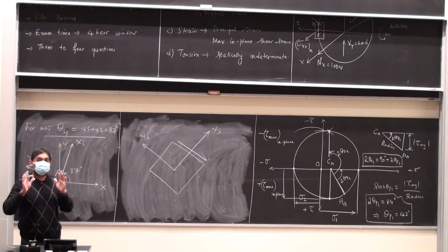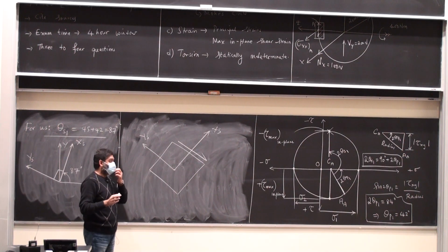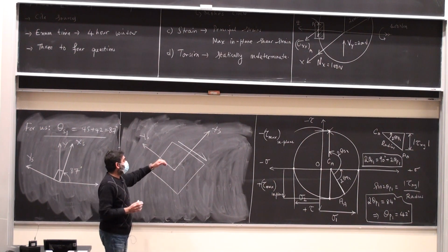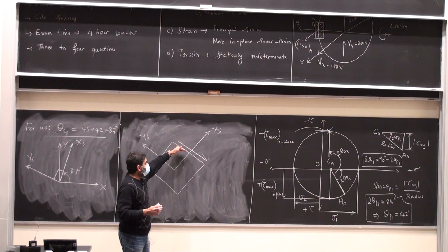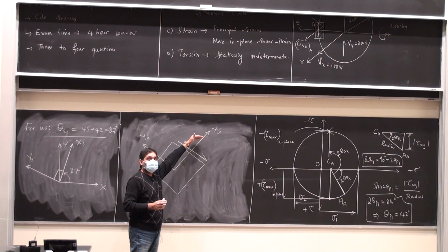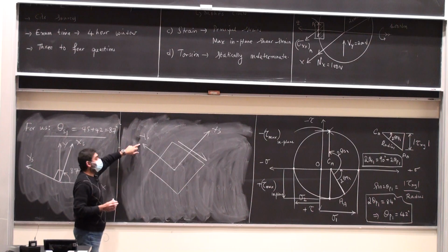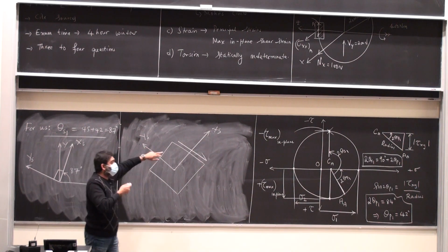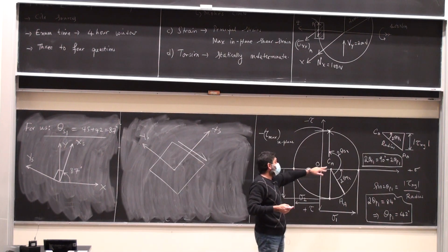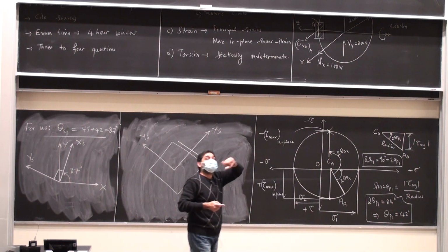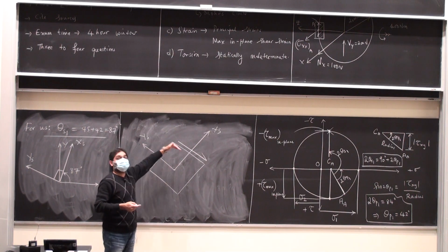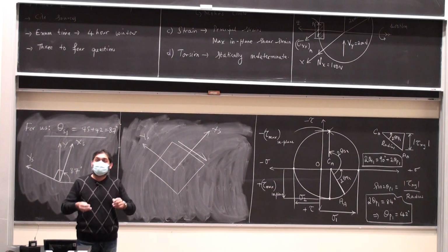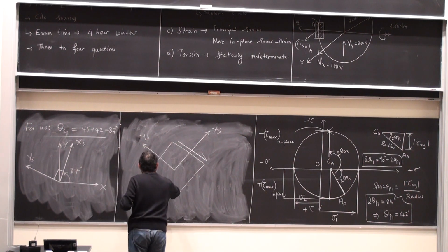According to the sign convention for shear stress, if the shear stress is positive, that means on the side where the area normal is positive, the shear stress has to be pointing in the positive y direction. That is not the case here, because as I reach from the reference line all the way to the first shear stress value, it is negative, which means it has to be opposite to the sign convention. And once I get one of these, I'm pretty much good to go, because the rest of them follow suit. So this is going to be up